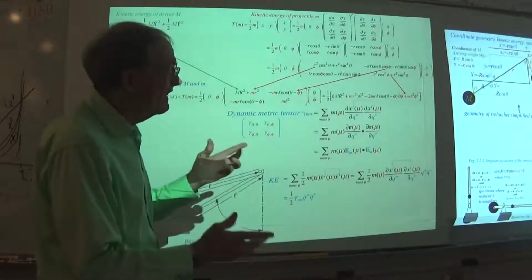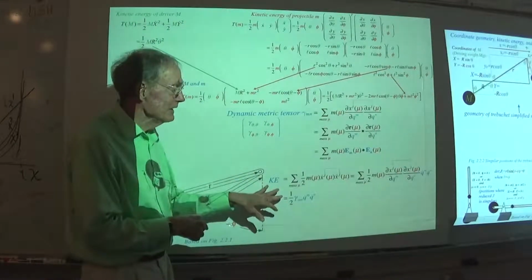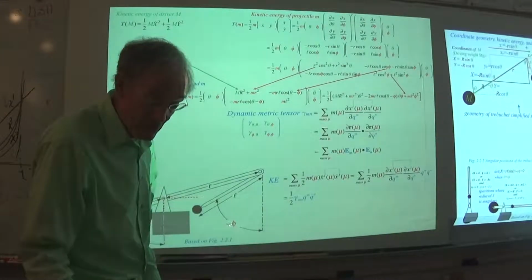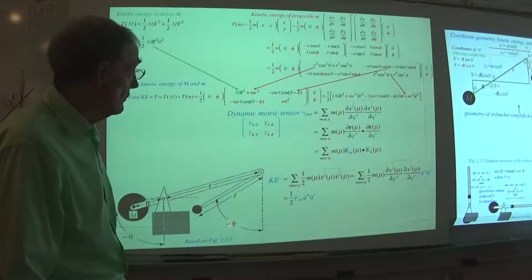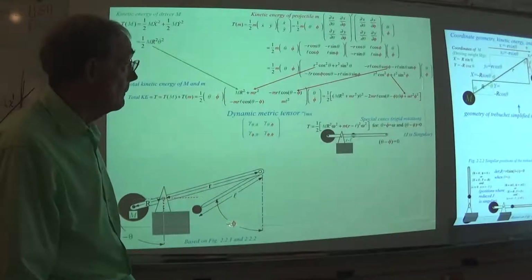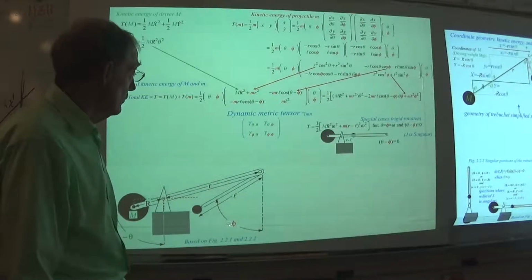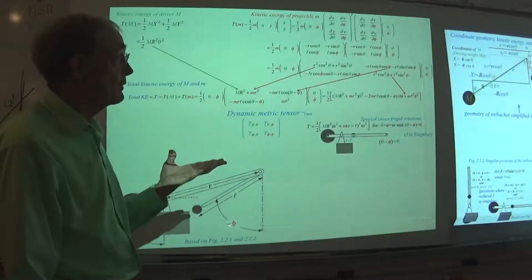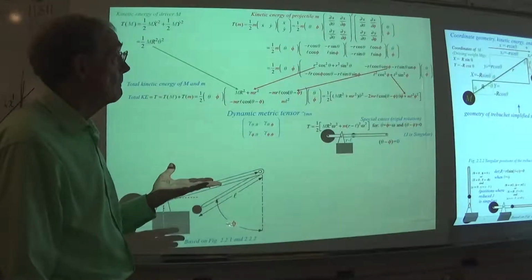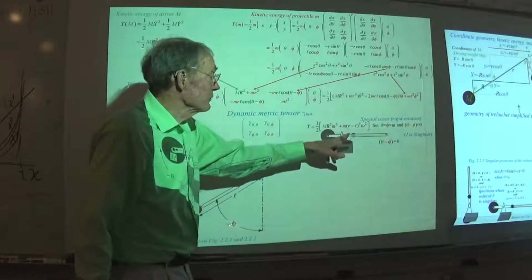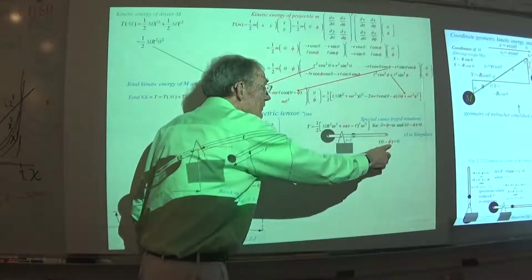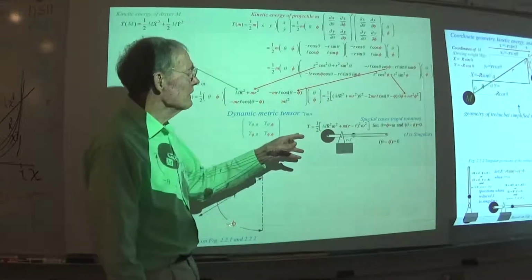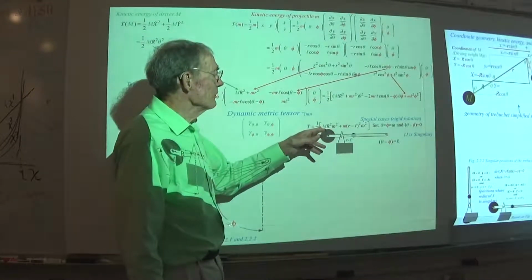So this is just bringing in a little bit of Unit 3 early into our discussion of Lagrange equations for Unit 2. So one of the things that you do when you're putting these things together is check it out for special cases. If I were to put the mass right here so that theta minus phi was 0, I would kill the Jacobian and it would be singular. The determinant would be 0.